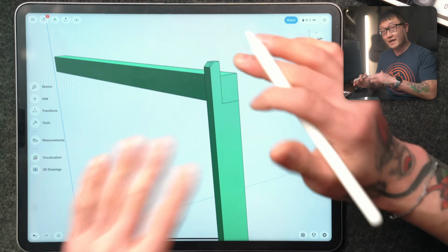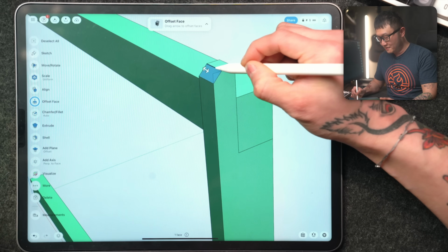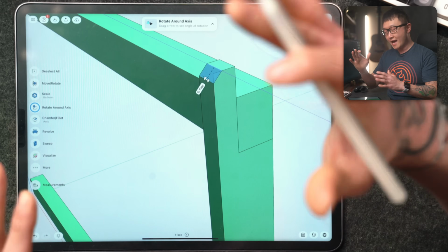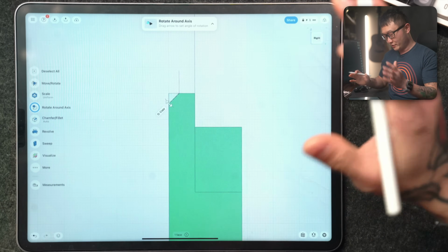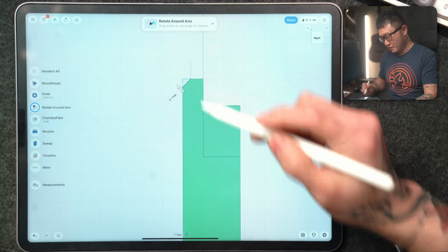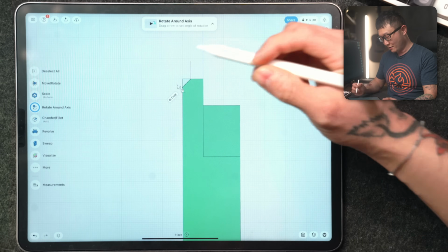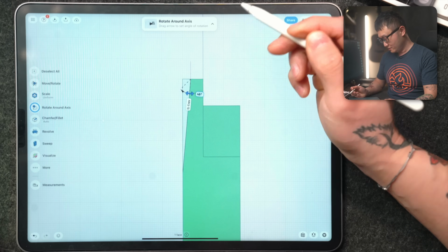We can actually change the angle of this chamfer, and we can do that by picking the chamfer surface and then the edge. And this edge becomes the axis that this chamfer surface can rotate about. Let's go to a right view so we can see how much we need to rotate this. I want this corner here to be lower than this corner. I think that would look pretty good. So let's, yeah, right there, 40 degrees.